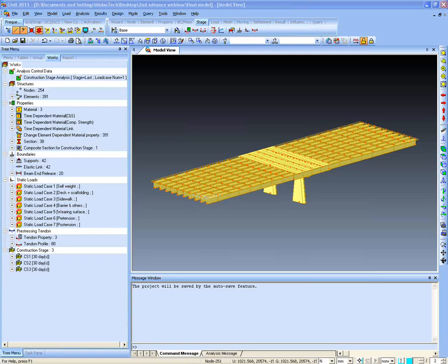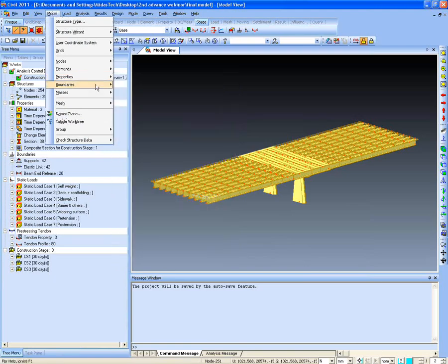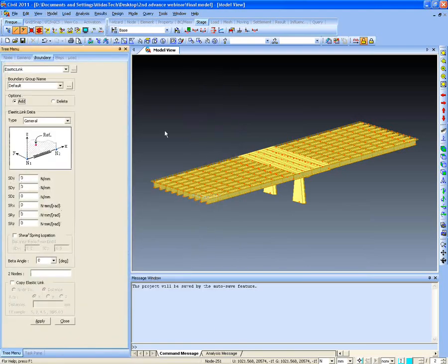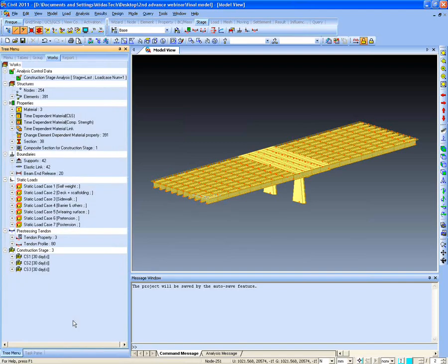There is another question from Mr. Chia Hun Lin. He says, what is the difference between the rigid link and the rigid elastic link? Well, in principle, there is no difference between rigid link and the rigid elastic link, but with elastic links, there are certain internal calculations that the program can perform.